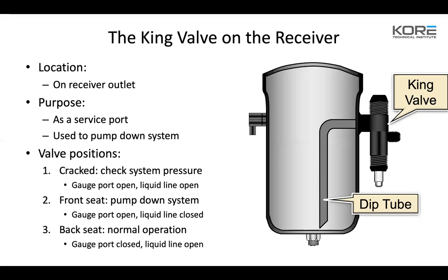The other thing is right here, if you're looking at my cursor, there's usually a packing nut. Some of these are packless, but on some of the bigger king valves, there's a packing nut there. If you have a leak there, just gently tighten it. You don't need to get on it super hard. We're talking about brass components. It's soft metals. So you just want to snug it up until it stops leaking. If you get on it too hard, you're going to damage the valve.